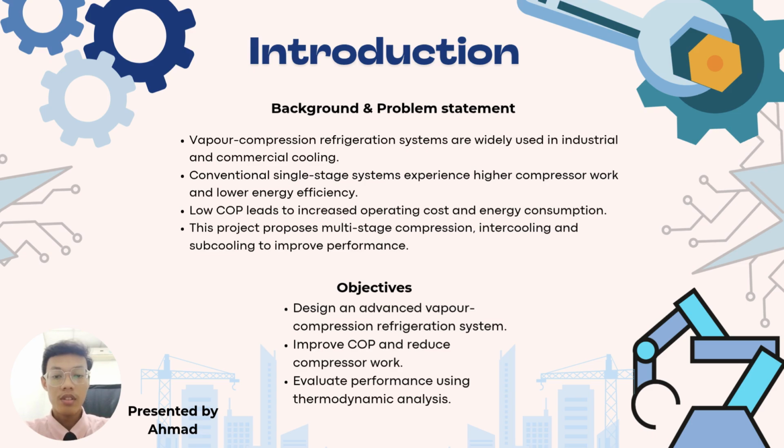However, conventional single-stage systems often have lower energy efficiency due to higher compressor work, resulting in a lower coefficient of performance, or COP. Therefore, this project proposes the use of multi-stage compression, intercooling, and subcooling to improve system efficiency, reduce energy consumption, and achieve a higher COP.